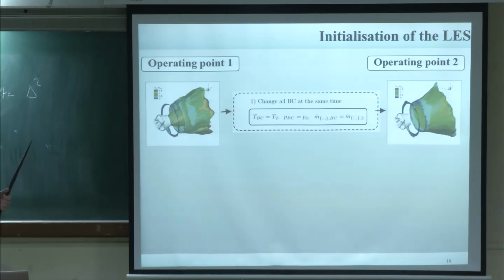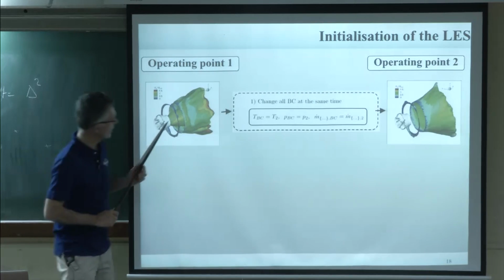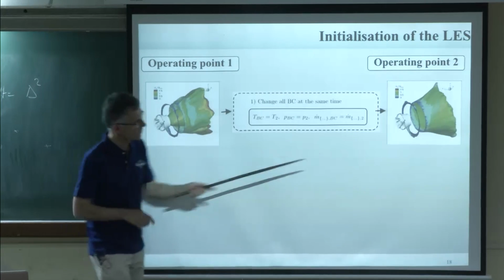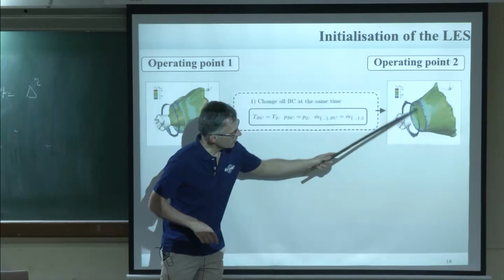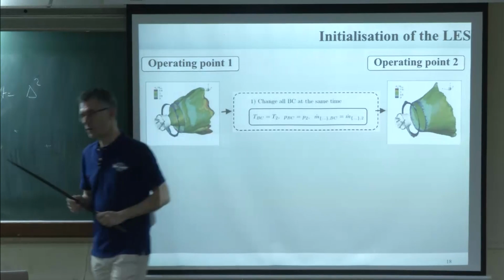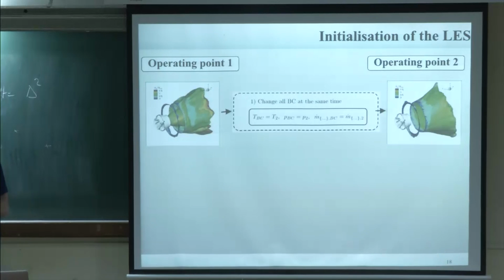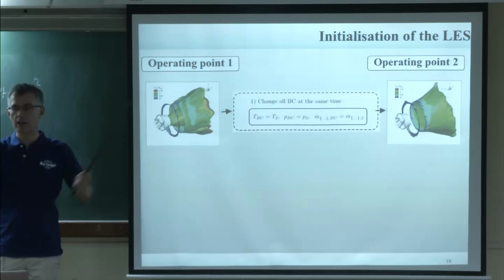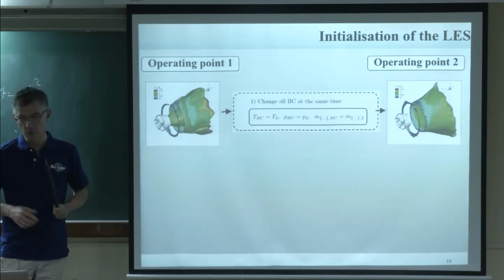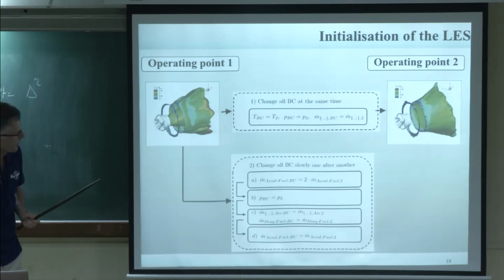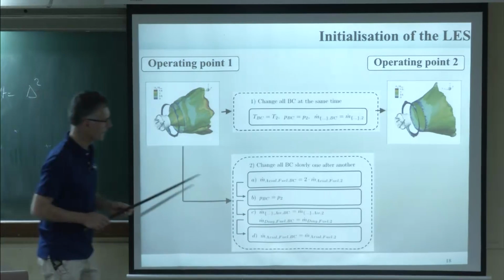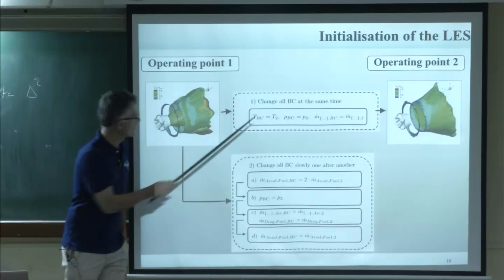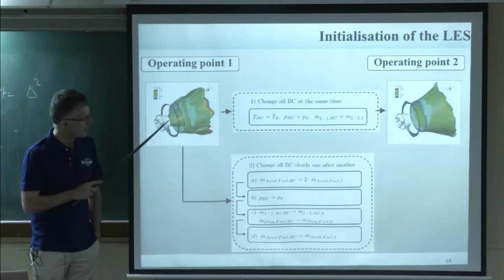And when we do that in the LES, what's happening is that this zone here quenches. You see it's here, it's gone. It's only stabilized on the side. The student who did it in the LES changed everything at the same time, boom, and then we went to that point here. So we told him, why don't you do it more slowly? First thing is, before you go to that point here, put more fuel in the pilot flames.